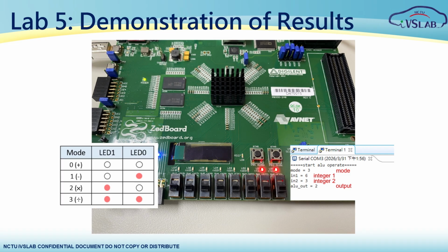This proves that when the CPU issues computational commands, it also successfully commands our hardware peripherals through our custom iLite registers. Now, feel free to modify the input values and operational modes inside helloworld.c yourself, re-execute the program, and observe how the system dynamic outputs change in response.